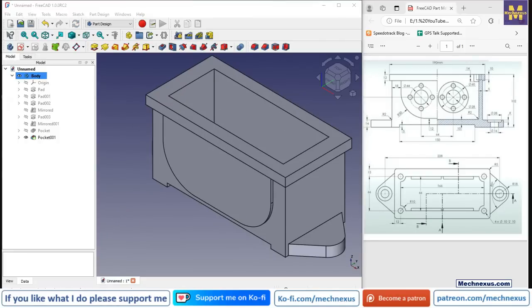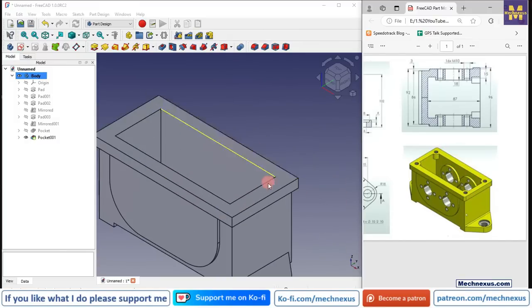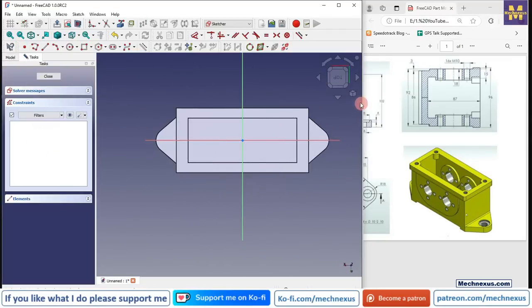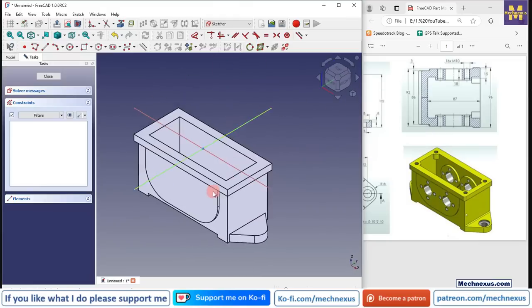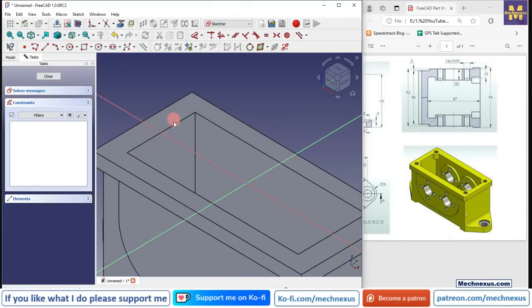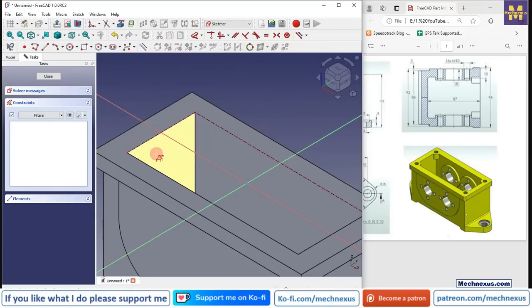Now let's move to the next feature, which is to add a material at these 4 locations. And to understand in isometric view, we are now going to make these features. So select the face and click on the sketch, switch to the isometric, and from here switch to the flat lines, and we will project these edges. Click on the project geometry, project this,